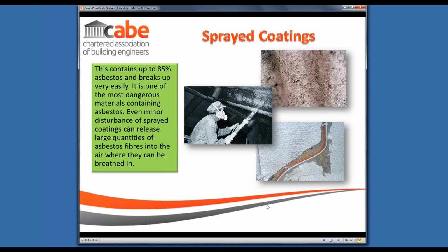If you're looking at something like a simple 75, 100mm core drill into a ceiling that may or may not contain asbestos, the main issues there are to take the appropriate precautions when you're doing the work to ensure that you're protected from breathing in any fibres that may occur, and to do the best possible to capture fibres as they're produced by the process.